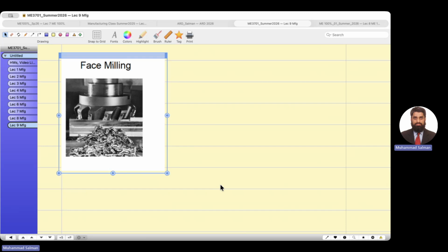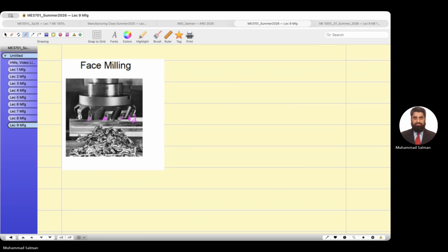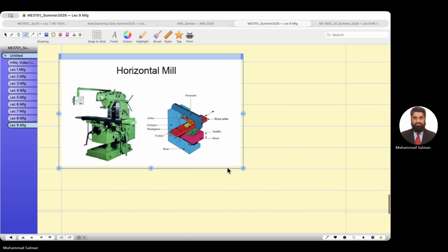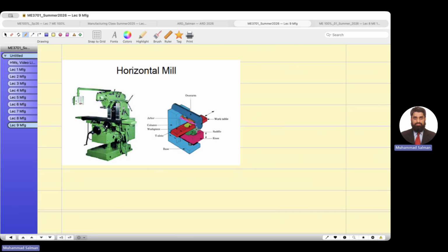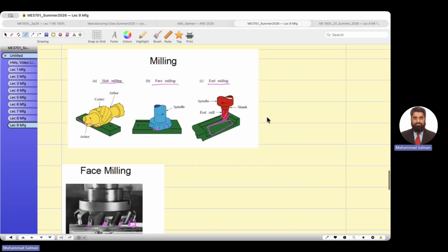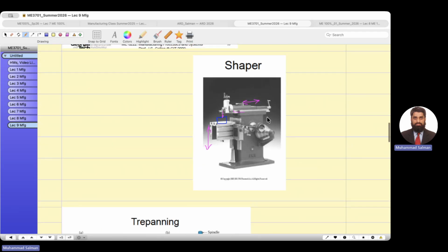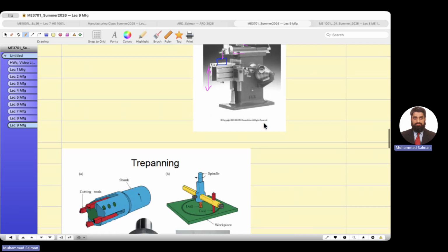This is the face milling operation being performed here. So you see, initially the height was big, and this is the depth of cut, and you see the tips. Some of them are diamond shaped. We call these diamond shaped tips. And this is another machine tool which is like horizontal milling. When this overarm is horizontally placed, this is a horizontal arbor, and when this is vertical, it's like a drill press. Where is that drill press? Let me show you over here.